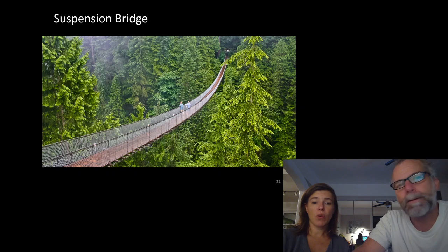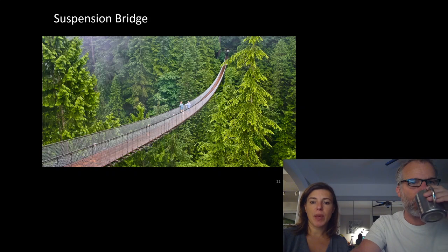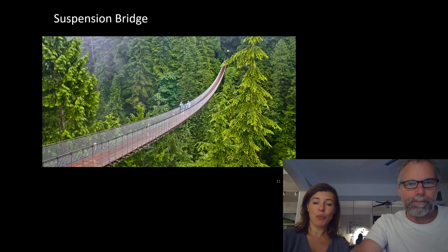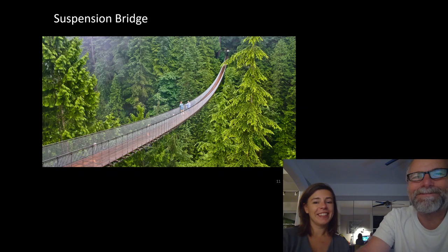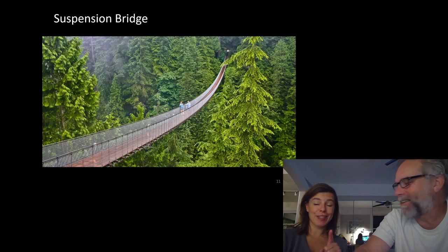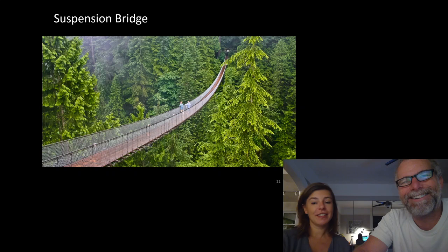And so obviously no deflection criteria, or a very, very, very loose deflection criteria, because it is supposed to deflect. And vibration criteria becomes more about protecting the bridge, not about making people feel comfortable. The premise is that you're probably already pretty uncomfortable when you're up there. A little bit of vibration isn't going to add to it. Yeah. And I've walked across this bridge, and probably a bunch of you have, and you feel the movement for sure. Yeah, I was uncomfortable. And if you've watched Shrek, Donkey does not like it at all.